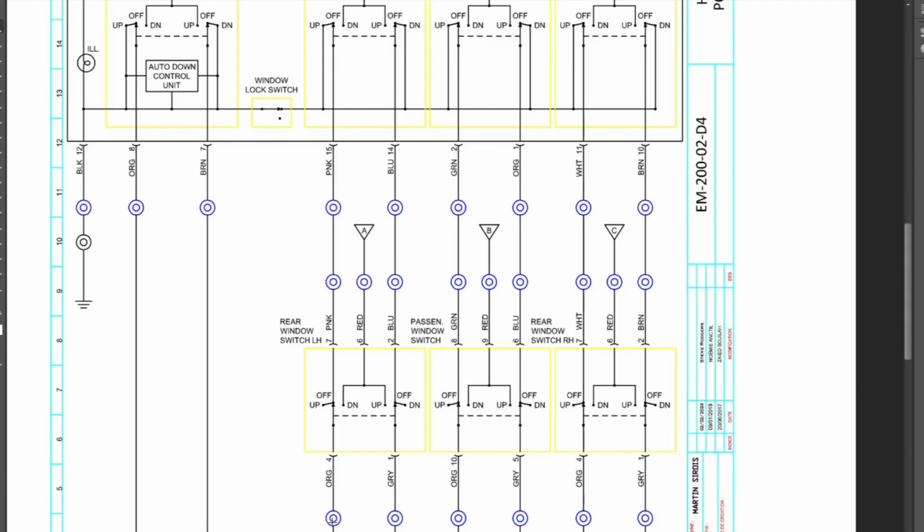So I suggested to you that power door locks, power seats, power windows are more often than not, both leads, when you do not touch any switch, are connected to ground. So it's a very quick and easy way to start dividing and conquering this circuit, because you can literally split in half your problem in very short order. So let's take a look at this orange circuit. I suggest to you it's connected to ground.